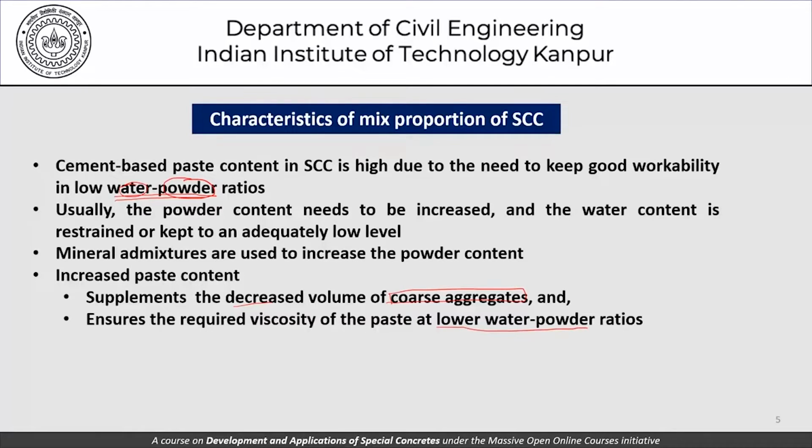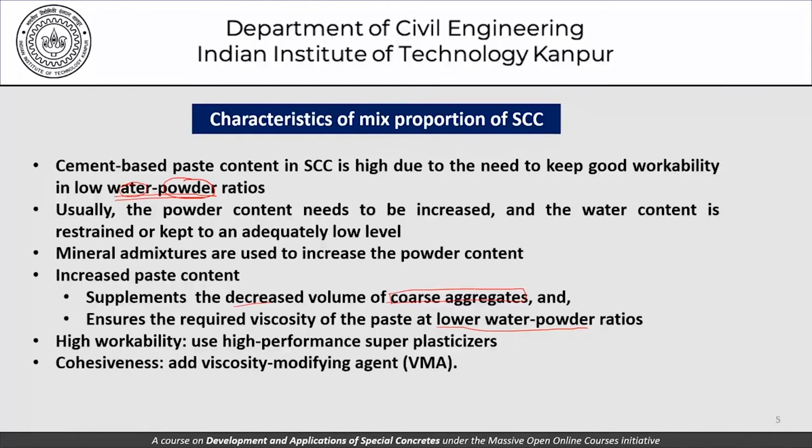So if we increase the powder content, the viscosity or the segregation resistance of that paste increases. High workability is also achieved through using high performance superplasticizers, and we get cohesiveness from using the viscosity modifying agents.